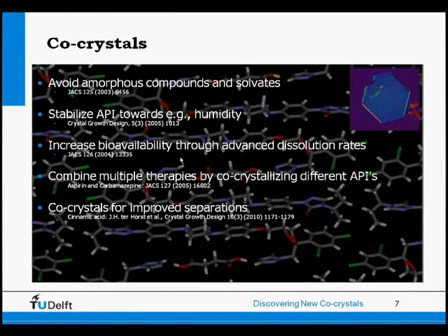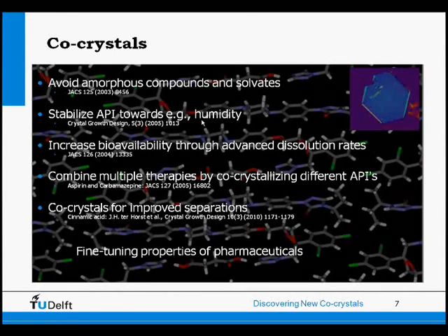Another interesting thing for co-crystals is that you can use them in your process to improve your separation. So for instance, make crystals that are more easily filtered off, so that your process is much faster. So you can actually fine-tune properties of pharmaceutical solids by using co-crystals.